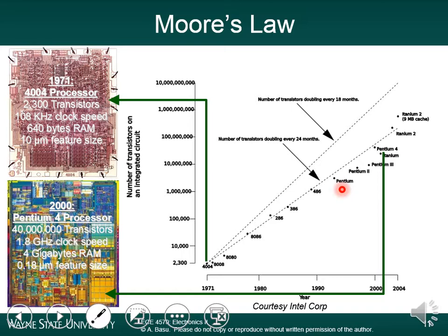Right now it's starting to sort of level off. The reason for that is at some point, your transistor becomes so small, it becomes almost the size of individual atomic layers. And when you make it that small, you start to see other effects. You start to see second-order effects. You start to see problems with short channel effects, where the MOSFET, if you're using it as a current source, doesn't behave reliably as a current source.